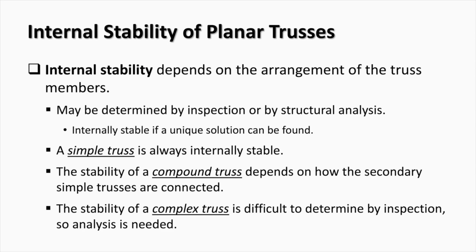The internal stability of a truss depends on the arrangement of truss members and can be determined either by inspection or by structural analysis. If the truss is internally stable, a unique solution for internal forces in the truss can be found. An unstable truss will have several solutions.